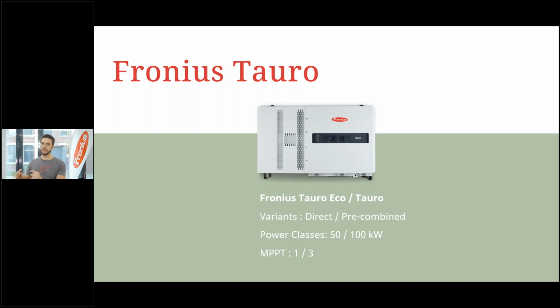So it has pre-configured MC4 plugs at the bottom. If the position of the inverter is a little further away from the modules, from the arrays, and you would have to cross a bigger distance on the DC side, you can choose the pre-combined option because it has not MC4 connectors on it, but it has big V-clamps, very big V-clamps, where you can connect up to 95 square millimeters of DC cable to it. So you can pre-connect all of the modules on the roof, on big combiner boxes, for example, and then you run down big DC cables to the inverter. So 2 options for 2 scenarios.